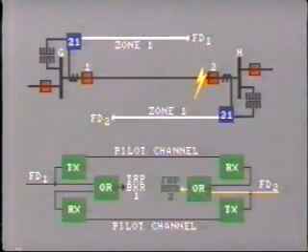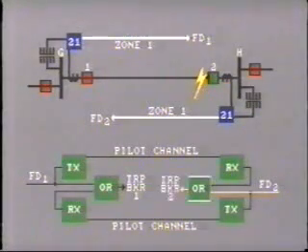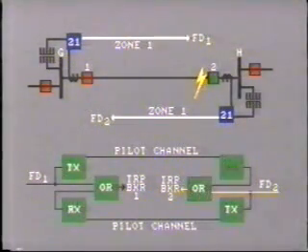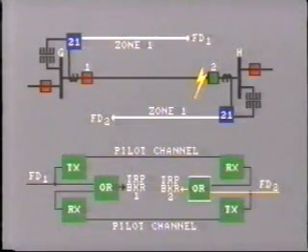The signal passes through the box and goes on to trip breaker number 2. The OR designation means that the breaker will also trip for a signal coming in from the receiver. Either one of the signals will cause the breaker to trip. That is, one or the other.